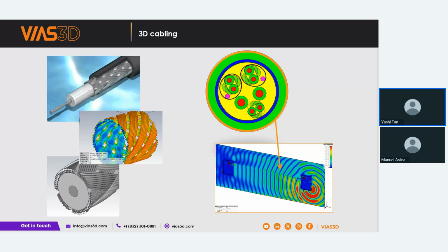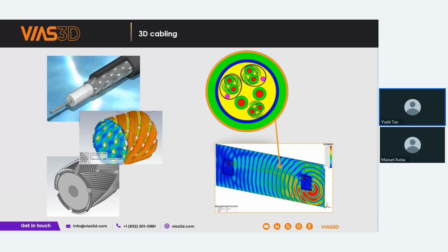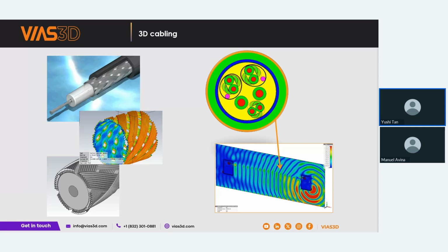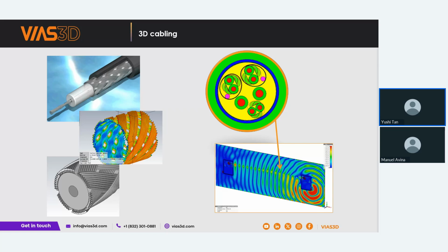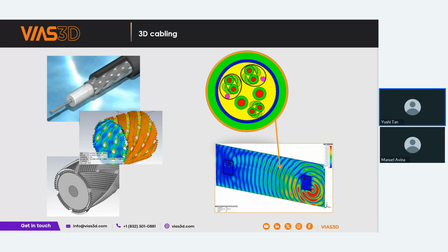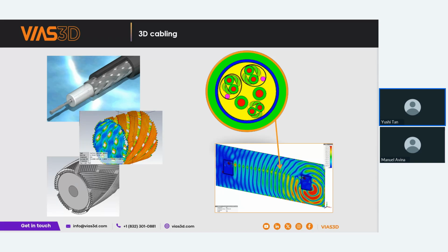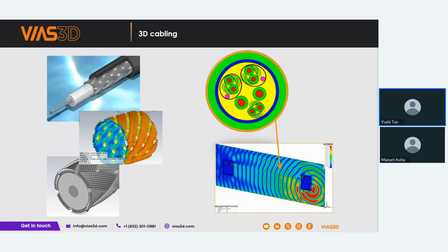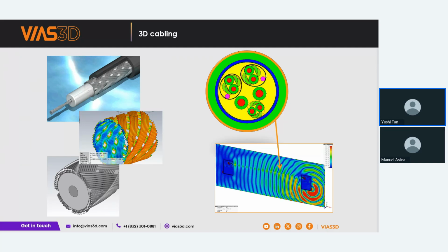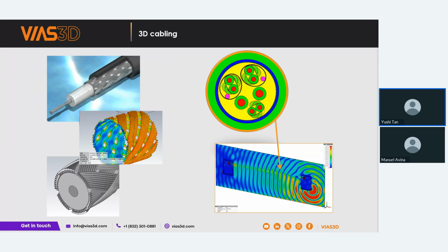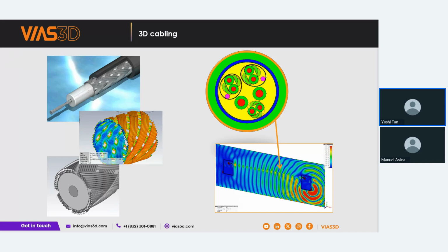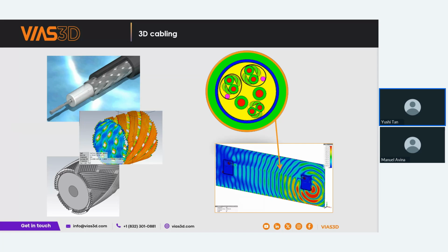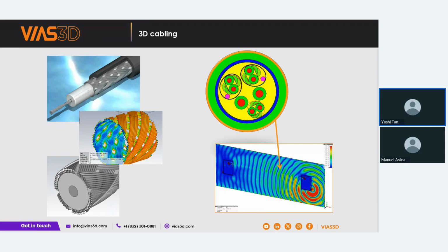Right, so full 3D is generally not feasible for these types of situations because of the complex geometry captured, and also the length of the cable may be a lot longer compared to, let's say, the details of the model. So the aspect ratio is quite big, so that makes the simulation very inefficient when you have that kind of scenario. And multiple techniques can be employed to make this more manageable. You can leverage these techniques to capture the signal integrity part and also bring that into full 3D.